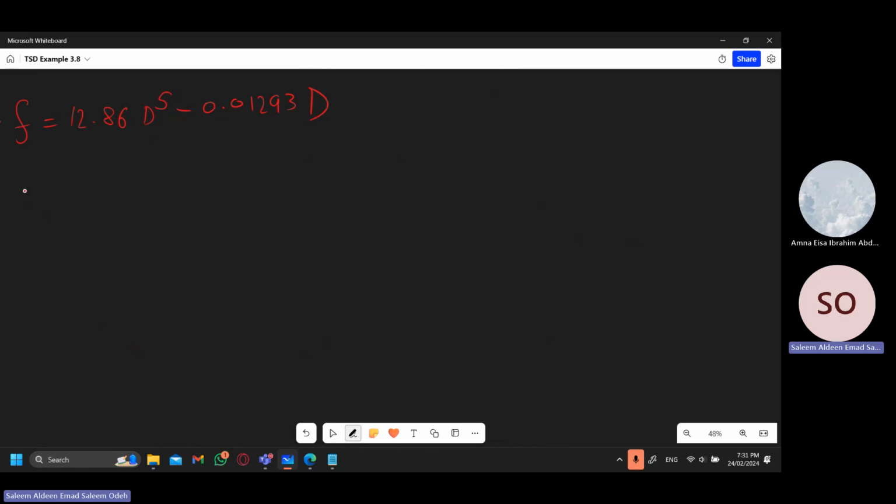And now we will try to find the Reynolds number. As I mentioned last example, to find the friction factor you need the Reynolds number and the roughness over diameter ratio. Now, the Reynolds number can be found using this equation, specifying this is density, not pressure.